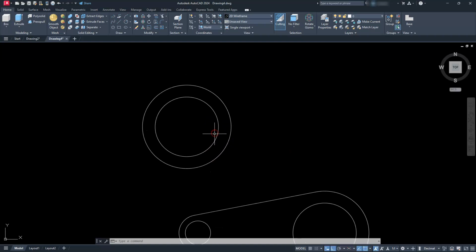Now, what I was referring to before is that I need to create a circle that's located 100 away from here. I always kind of think about two different options of what I can do. First option you can do is that you can just copy this circle over. And actually, if I want to be a little bit more proactive, I can copy both of them over and change them in the properties window. But in this case, I just wanted to show you that if I wanted to draw a circle in reference to this center away from it, we can do that as well.